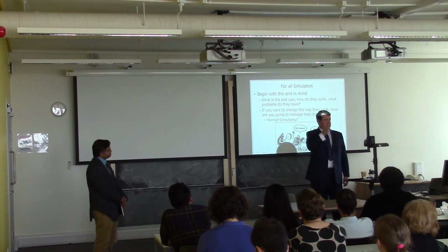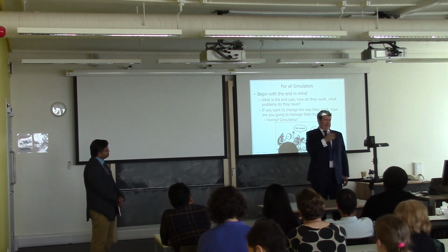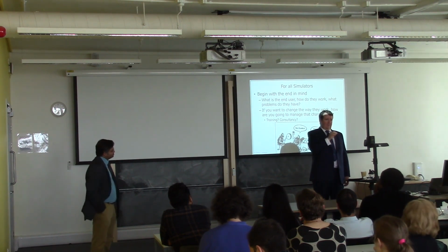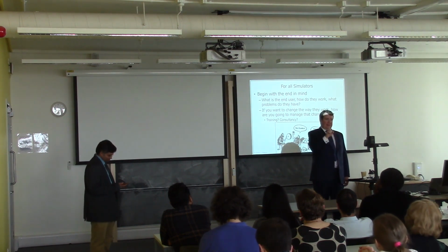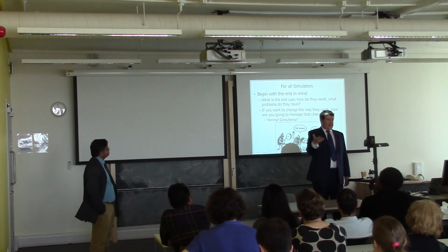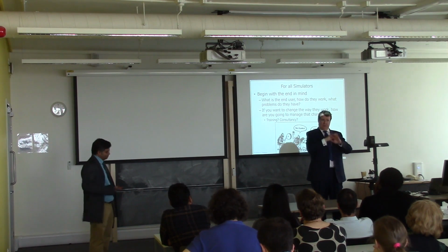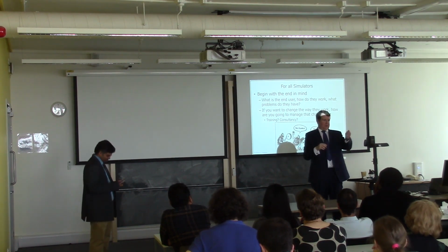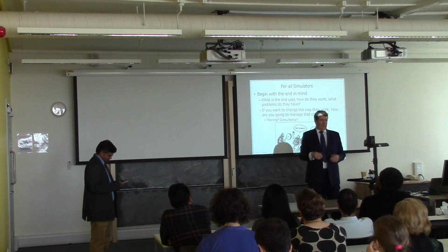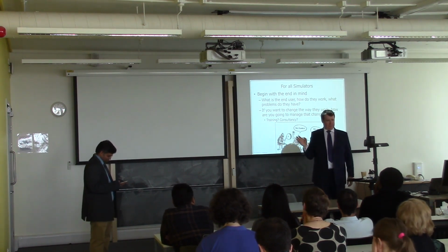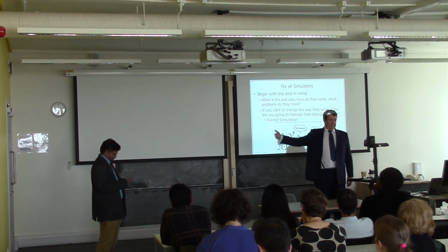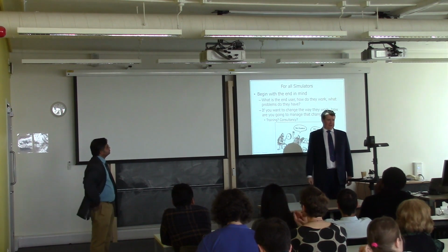So it stopped being the world's largest one, and they were happy with that, they convinced themselves. Importantly, it would work for 99.9% of cases, and we said, in the event of that 0.1% of cases, this is how you have to operate it. You wouldn't have hydrate blockages, you just need to start shutting in high water producing wells. So it would be painful, but it wouldn't be as painful as a blockage. It just means you can't produce as much gas as you would if you'd bought the largest injection system.